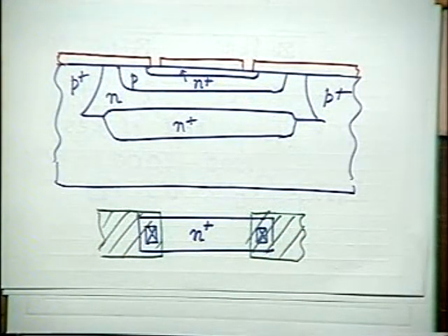I want a pure resistance of 30 ohms there. I do not want other components automatically built in with that. So what should I do for that? Any one of you can suggest how to inhibit that. Emitter and base, you don't allow this junction to be forward biased.